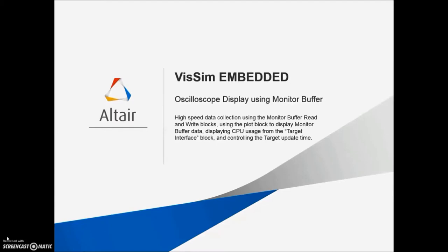Specifically, we'll discuss the following topics: using the monitor buffer to record high-speed data from the target, configuring the plot blocks to display the monitor buffer contents in an oscilloscope-like manner, displaying the target percent CPU usage, and controlling the target update time.